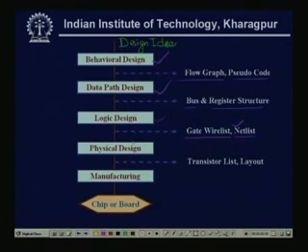And now, these gates, again I partition, because one gate I can always realize by some transistors. So, this we call the physical design. The output is a transistor list, that means a set of transistors assembled together form a gate, and this we call the layout, how this set of transistors is placed within a specific area.